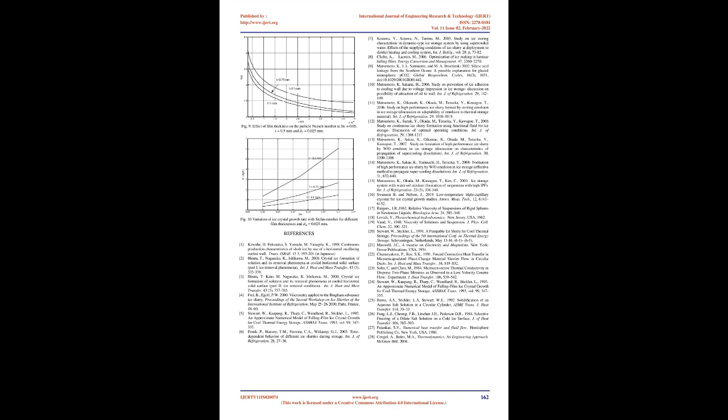It has been observed that for the film thickness of 0.5 mm corresponding to Re equals 200, the local Nusselt number increases along the plate surface, approaching its maximum value at the middle of the plate, then decreases slightly to an asymptotic value of 590 at the end of the plate. This is due to the enhancement in the effective thermal conductivity of the ice slurry not being equivalent to the increase in the temperature gradient at the wall, consequently decreasing the heat transfer coefficient along the plate surface.